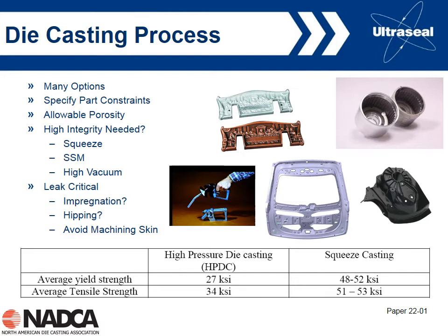The bottom casting is a shock tower for a BMW car produced in this country. This casting is structural, safety critical, so when the car's in a crash, the casting's got to fail in a ductile manner. It's got to bend and absorb energy during the crash. If it just shatters, then it's not going to absorb any energy, and that's detrimental to the passengers in the car. So the casting has got to be very ductile. If we have porosity, that's going to reduce the ductility. It's also thin walls. We need the low porosity we just talked about. So another example of high vacuum die casting.